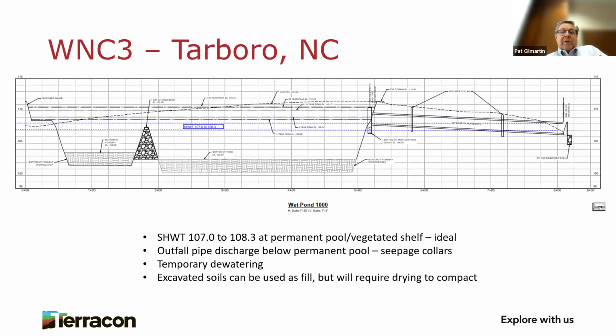For the outfall pipe, the civil engineer went ahead and did design some anti-seep collars. And you're like, wow, that thing's really flat. There's about a 2-foot head difference between the permanent pool and the outfall pipe elevation. They didn't ask us to run a seepage analysis of those existing soils. Well, they're not existing soils, because to install the pipe, they're going to have to trench it.